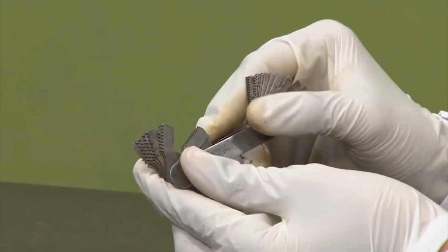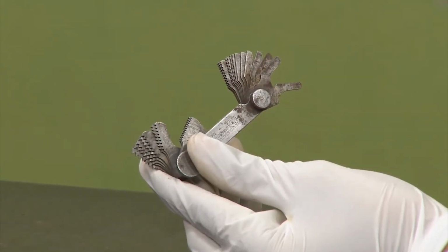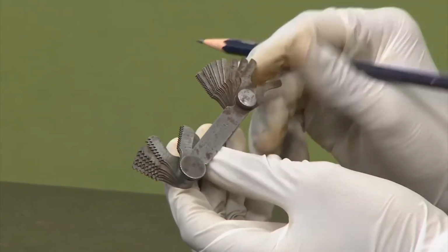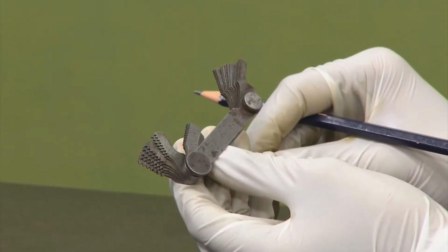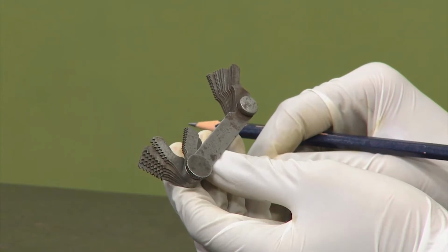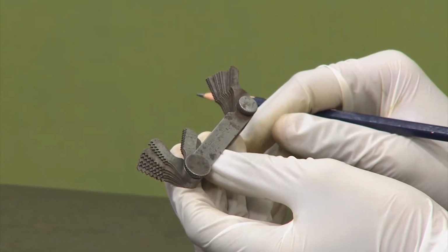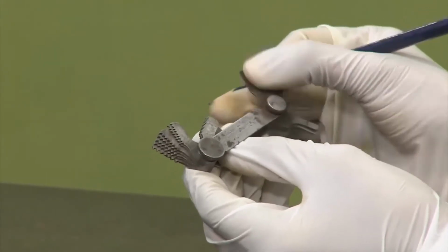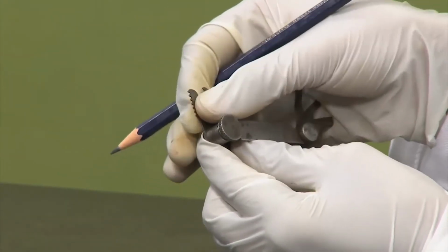I would like to correct myself, it is different pitches of the thread, the profile is same, it is actually the metric thread gauge. We can have metric thread gauge, Acme thread gauge, then Whitworth thread gauge. For all different kinds of threads we can have different thread gauges, and this is a metric thread gauge which is having range from 0.25 to 2.5 mm pitch. The smallest leaf here has the pitch 0.25 mm and the largest leaf is 2.5 mm.